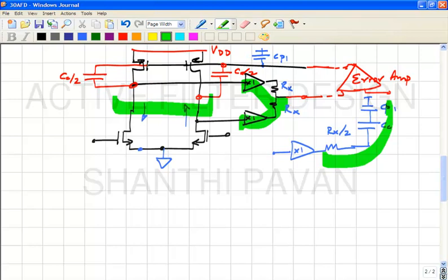The loop gain of that common mode feedback loop is simply the product of the common mode gains of each transconductor. So keeping the loop gain less than 1 in magnitude is equivalent to saying the common mode gain of each one of the transconductors is smaller than 1, correct? And therefore the magnitude of the loop gain is much smaller than 1, and therefore you are okay. No. Yes.